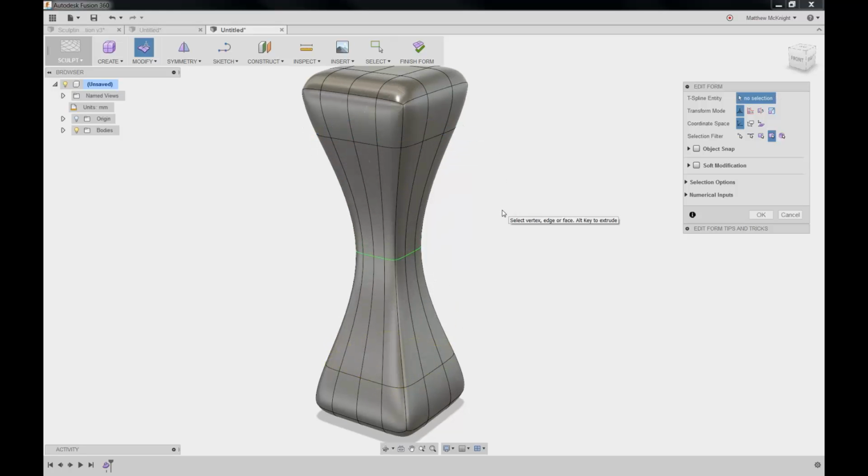Now, if you found that, I actually don't want to have its symmetry around the top and bottom, I want these edges around the top, but I don't necessarily want them around the bottom. In this instance and numerous instances, you can delete edges by group selecting them, and simply hitting the delete key on your keyboard should delete them.